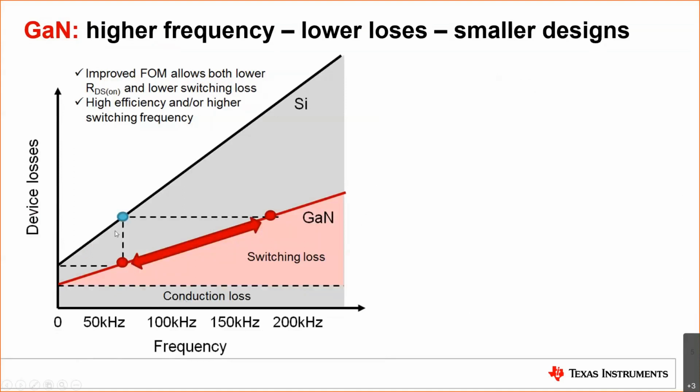And if you see now, for example, this point silicon and want to compare what can it bring for a GaN-based design, it gives actually now 2 interesting design options for the engineers. Either you can reduce the power losses and increase the efficiency of the design, or for the same losses, you can massively increase the switching frequency.